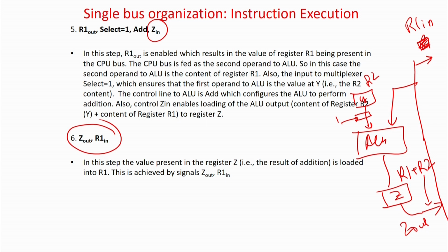If you compare load from a memory location and load from R1 and R2, these are register mode instructions and that involved a memory mode. So, there was a memory access. In the 1st stage you fetch the instruction from the memory, in the 2nd stage you actually have to get the operand from memory location A. But in this case we have never gone to the memory for the second time because everything was available in the register, right.